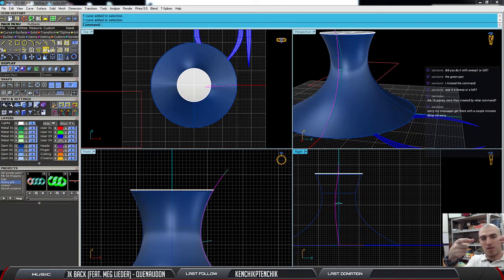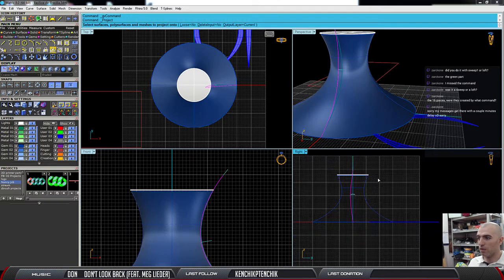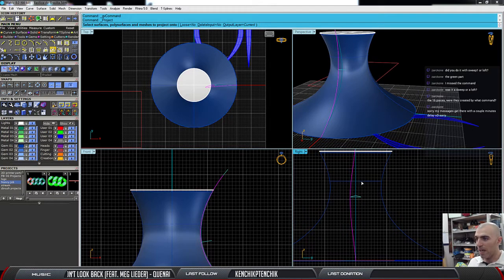So the cylinder is big, but on the surface is small. But I want a normal project. That's wherever the distance between the curve and the cylinder or the object, it will project it as it is. So choose this. I have to come to this viewport and choose the cylinder. Right click. It will project it all the way through.